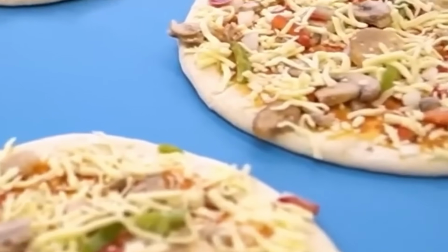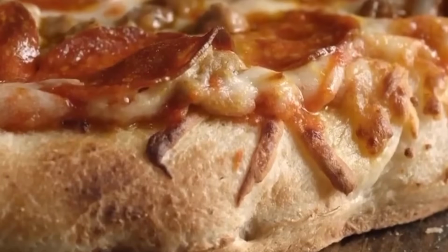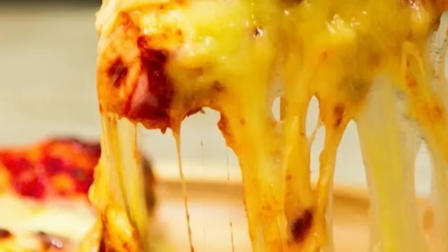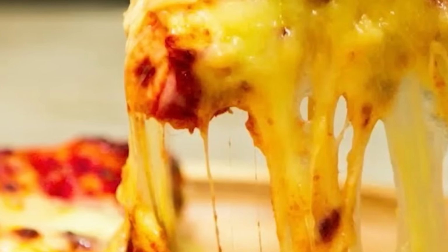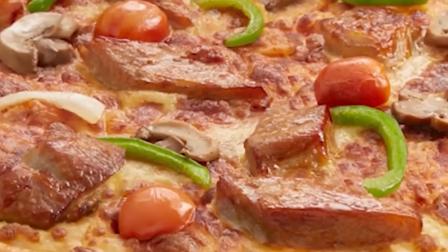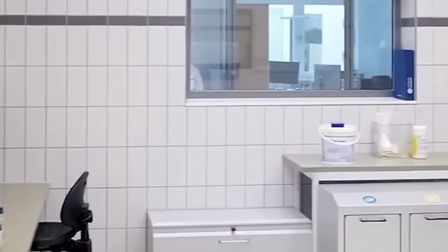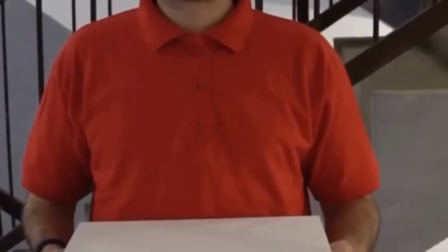The pizzas enter a conveyor oven with a stone or mesh belt and a controlled baking chamber. Top and bottom heat are separately adjustable using electric elements or gas burners. Baking time is generally between 6 and 7 minutes, depending on pizza size and topping load. The oven is divided into thermal zones which apply different temperatures to optimize crust and topping finish.